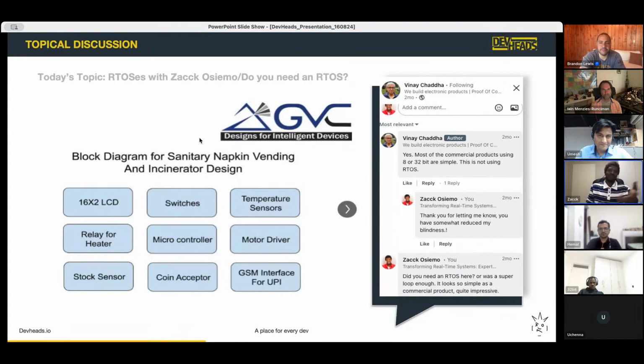An example of this is a commercial application by, I think, a company in India, and it's been in application for quite a while, and they don't use an RTOS. The thing I'm trying to explain here is, just because you're shipping something for the client or the end user to use does not mean you now need to graduate. Some people use the RTOS as the final layer of development: now we're done, let's put an RTOS on it and then ship it. You don't need an RTOS to ship. You can ship without an RTOS and you can still ship the functionality you need.